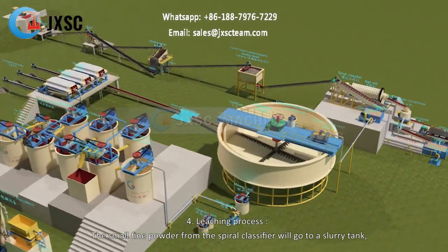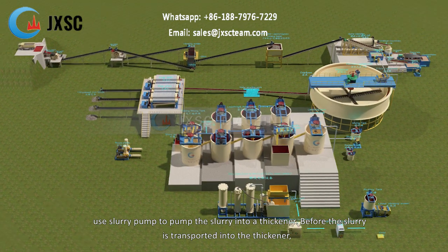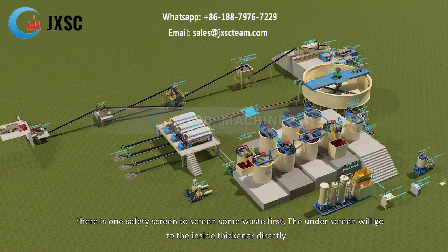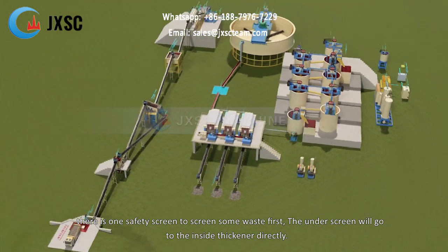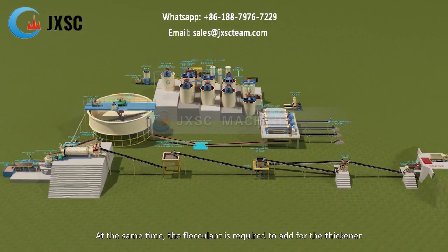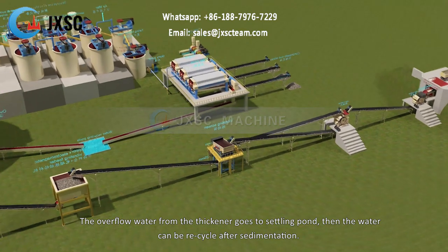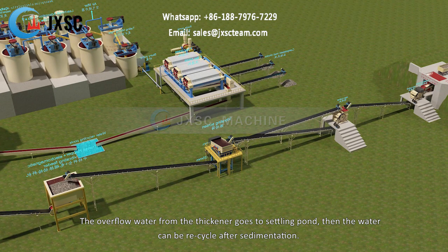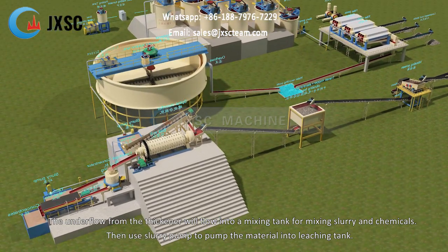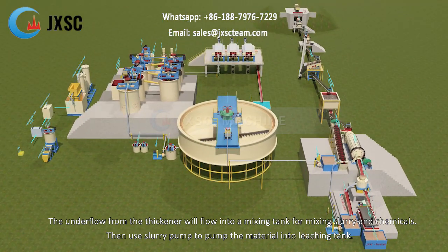4. Leaching process. The fine powder from the spiral classifier goes to a slurry tank. Use a slurry pump to pump the slurry into a thickener. Before the slurry is transported into the thickener, there is one safety screen to screen out some waste first. The underscreen goes to the thickener directly. At the same time, flocculant is required to be added to the thickener. The overflow water from the thickener goes to a settling pond, then the water can be recycled after sedimentation. The underflow from the thickener flows into a mixing tank for mixing slurry and chemicals, then a slurry pump pumps the material into the leaching tank.